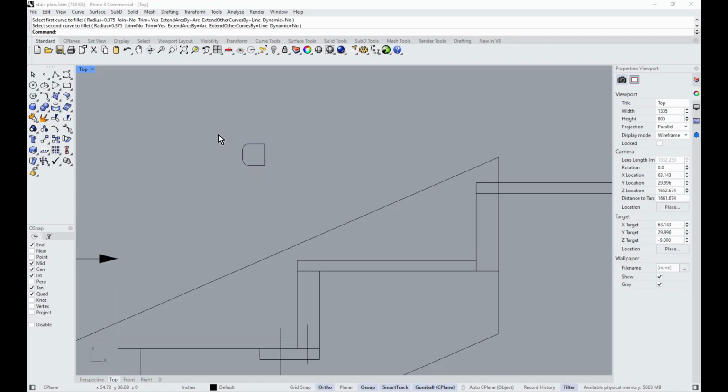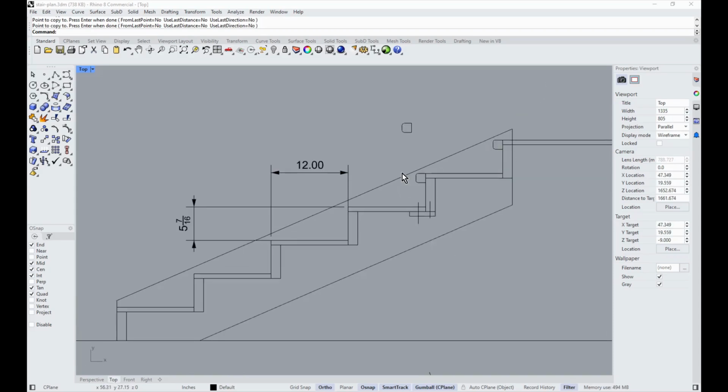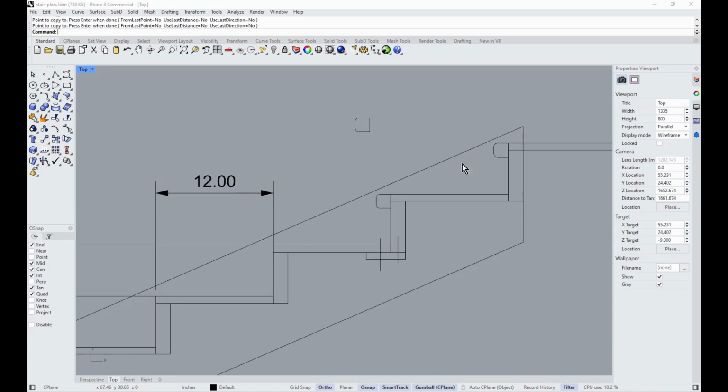So there we go, and it's all one combined thing, and you can copy this like so. And then this would just be bonded in and nailed to the end. You can change this as long as it's the same bull nose going down, the same dimensions. So that's a way to add a bull nose. You can also extend this over if you wanted to.